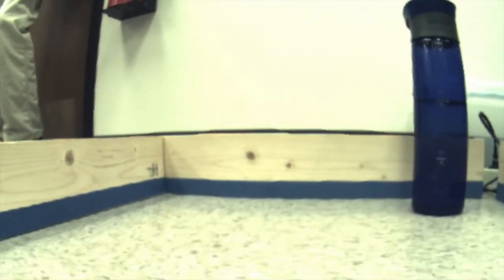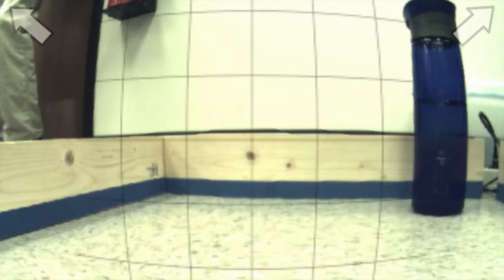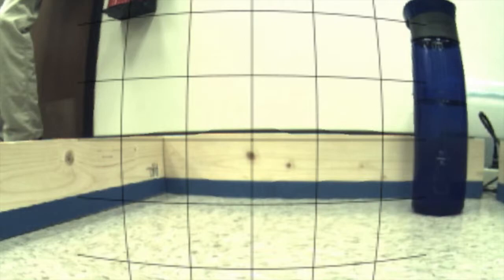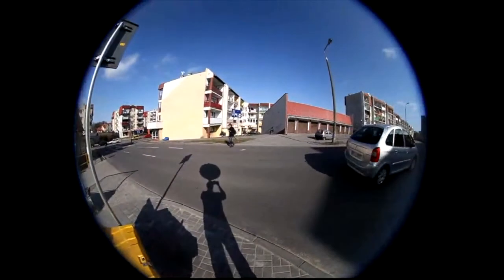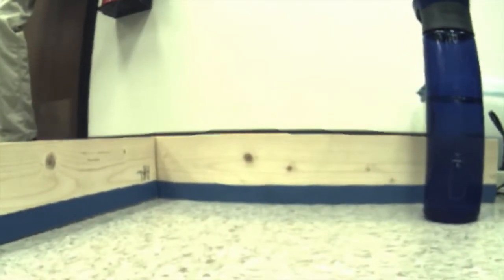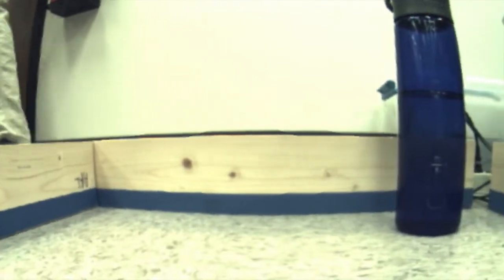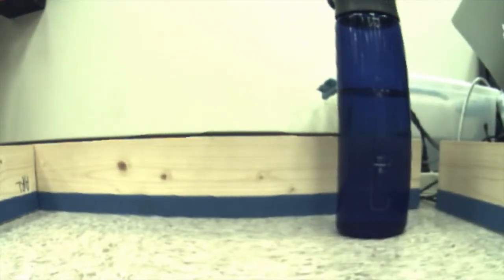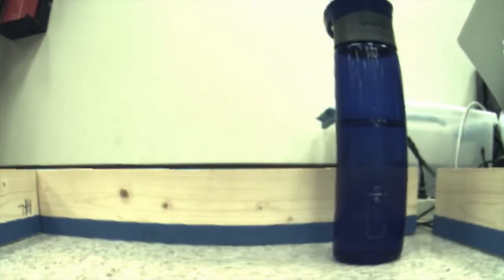Barrel distortion is the phenomenon by which pixels farther from the center of the image are pulled closer to the center point. This distorts the image to look as though it's being wrapped around a barrel. While this may be desired for some photography, this effect distorts the actual shape of the world, and in robotics, an accurate representation of objects in the world is necessary for navigation.